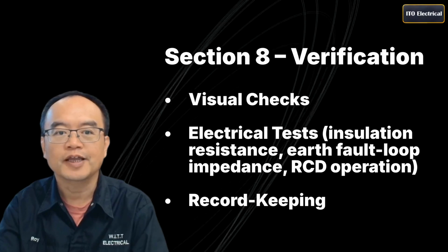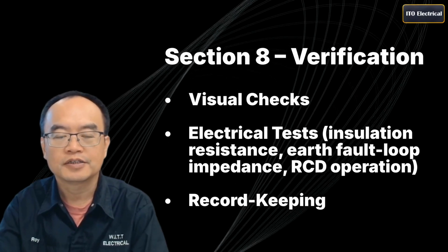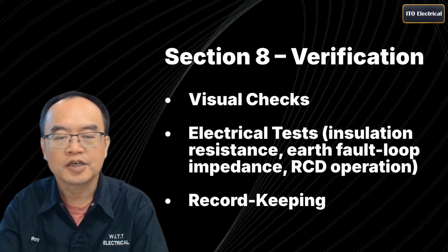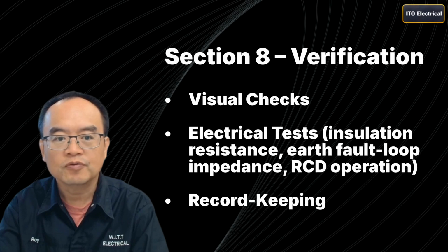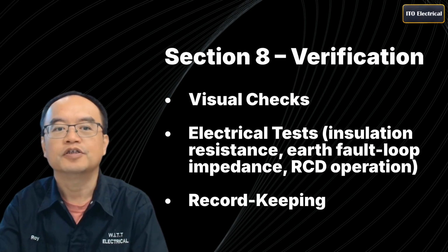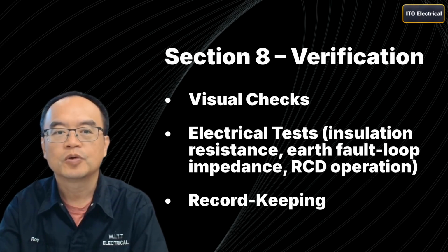You end with Section 8, which is all about verifying that the installation is done right. It involves visual inspections, thorough testing, like checking insulation or verifying your RCD trips properly, and recording the date of energization. This final step proves you've met all requirements.